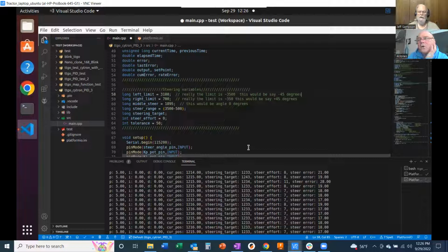And if you decide that you take it out and drive it around, and that's not working, then you can start playing with your I and your D. But if you're starting with the I and the D right now, I think it's just going to confuse you, and you're going to find out that it gets frustrating very quickly to get that to work. But it should actually work with just a proportional gain. So I just wanted to make that comment.